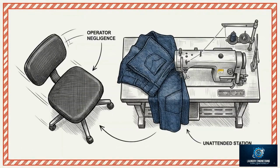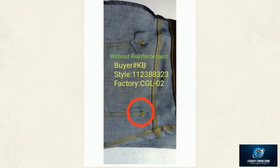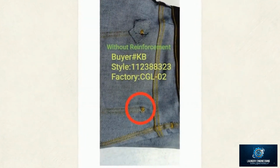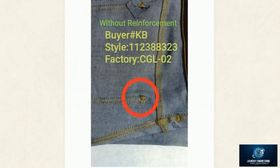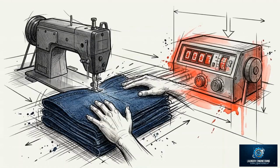Transitioning down the assembly line, we find a critical instance of operator negligence, the missing bar tack defect. Bar tacks provide essential structural support at a garment's inner stress points. Here, the bare inner stitching shows a complete absence of that required reinforcement. The root cause is deliberate. Operators are skipping the bar tack assembly station entirely to keep pace with high-speed production quotas.